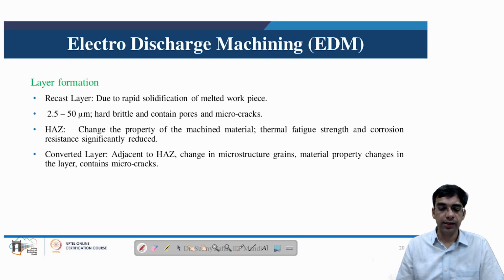So the recast layer is one of the important limitations of EDM, and this is generally formed due to rapid solidification of the melted workpiece.